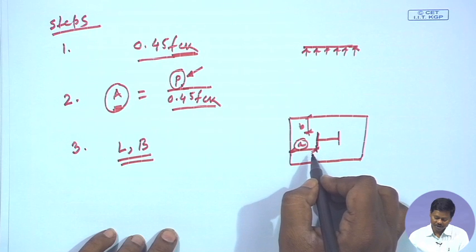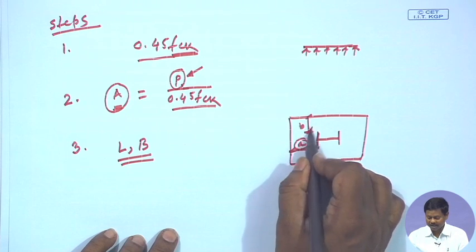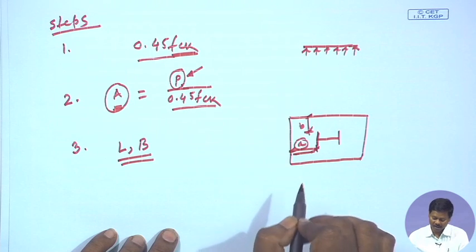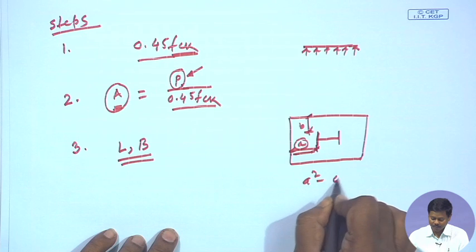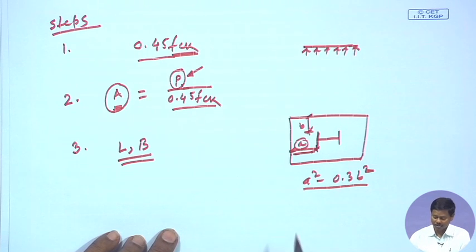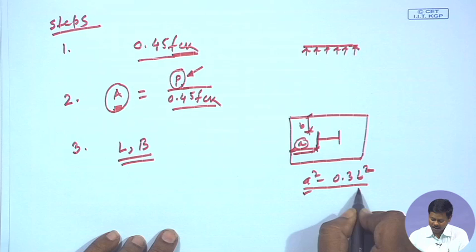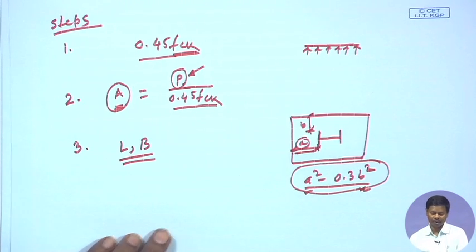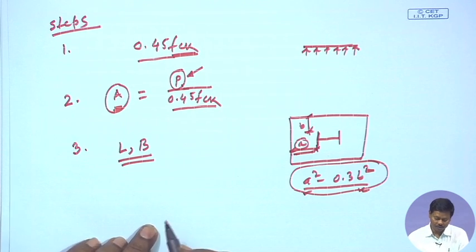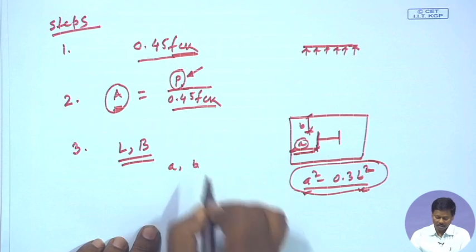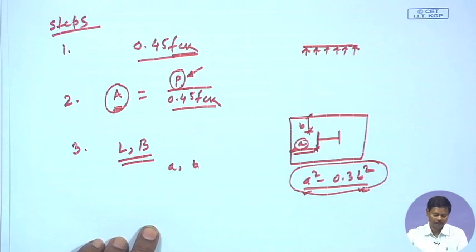However, if we consider the projections equal, then the projection will be a little less. Also, as we know, when we find out the thickness there is a term A square minus 0.3 B square. So, if we try to keep A and B as equal as possible, then it will become minimum. So, to make it economical, we will try to keep the projection lengths A and B as equal as possible, right.